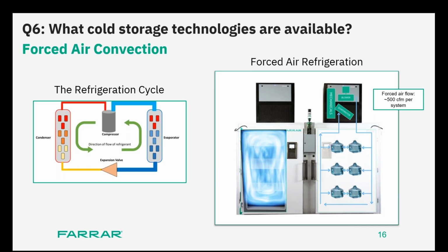It's just based on your application. If you're looking at long-term storage with low frequency of door openings, there's nothing better than cold wall, and we provide that support to you. As opposed to that, you're at a research facility where high frequency of door openings is really needed for sample assessment, then the forced air convection would be a fantastic solution to you. With that, I would like to make sure that I've covered both aspects of cold wall and forced air convection.